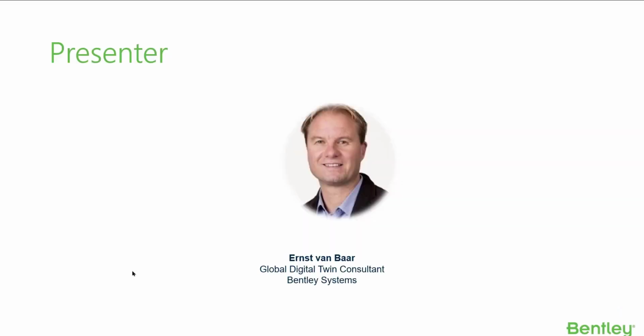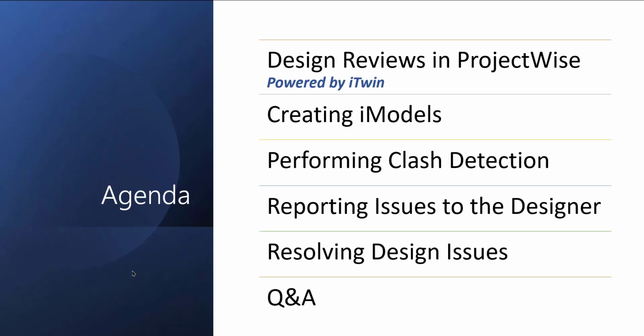My name is Ernst Bayer, working as a global digital twin consultant here at Bentley Systems, and we will cover how to do design reviews in ProjectWise, powered by iTwin, what iModels are and how to create iModels. Then we will do a multidisciplinary design review, create a clash detection test, assign it to a project member, manage the issues and solve them, and then synchronize it automatically back to the platform. So this is a closed-loop workflow which we're going to show you, and then we are open for your questions, so looking forward to this one.